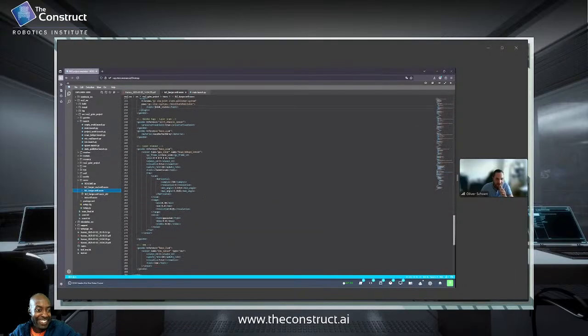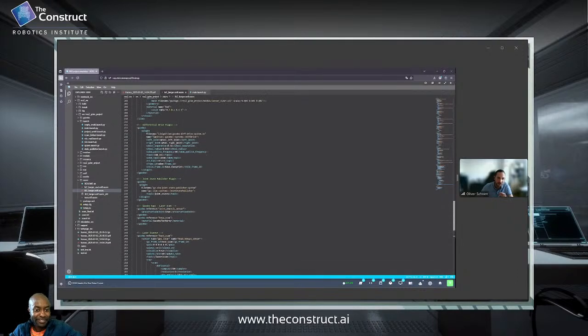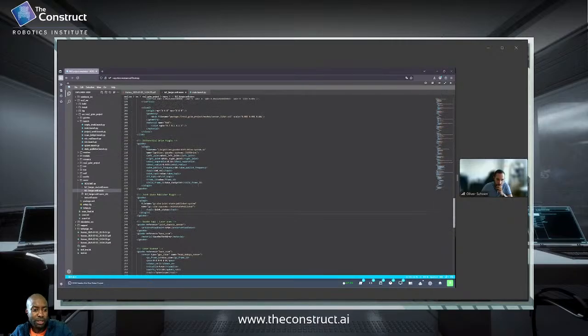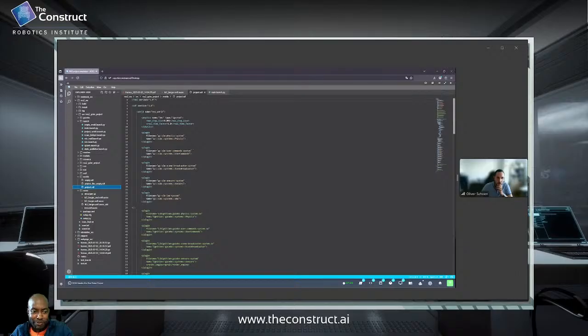It's all good. It's just general. My assumption is that for the robot part, we have the plugins that are directly connected to the robot. For example, the differential drive needs information of how the robot is set up, like the joints, like how the wheels are separated and so on. But in the world, we want to have these plugins to actually give information to the outside, meaning that we can connect it with ROS2. Actually, for the differential drive and the joint state plugins, they are fine in the robot description file. They're actually supposed to be there. It's just the other ones for the sensors that need to be in the world files.